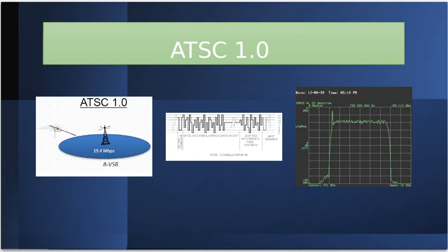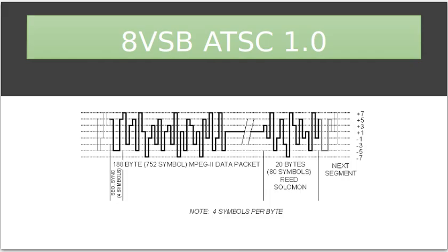It's still an analog transmission, but what they are transmitting is essentially digital bits from the video compression stream. And the modulation they used was called 8VSB, digital vestigial sideband. In a way, a fancy single sideband type scheme. So basically we had an analog signal that only had 8 discrete values, right? And this would be the baseband signal shown here. It occupies about 6 megahertz at baseband.